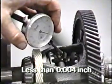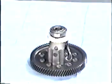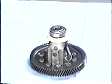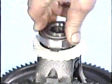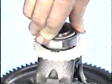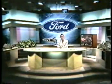If the backlash were not within specification, the differential would be replaced as a unit. Also, be sure to check the differential bearings. If they're serviceable, you can place the differential assembly in the clutch housing and measure for correct bearing preload. Most of the repair procedures for the transmission and the transaxle are similar. Four-wheel drive vehicles add another component to the vehicle's drivetrain, the transfer case.